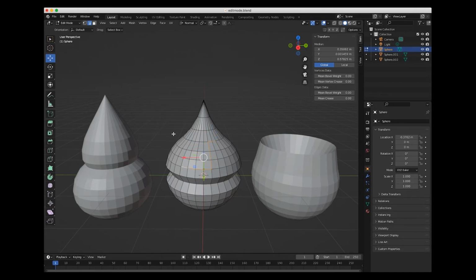But Blender has a selection way that chooses the shortest selection. So I can click that edge, and then I come down here and select another edge with Shift and Control, and it selects all the faces between here and here.